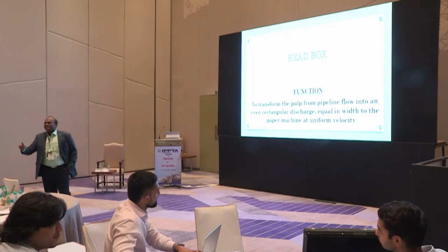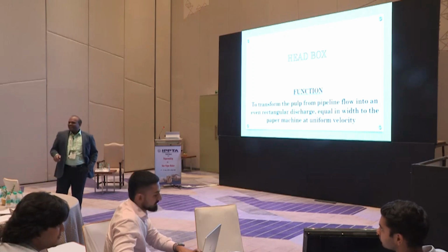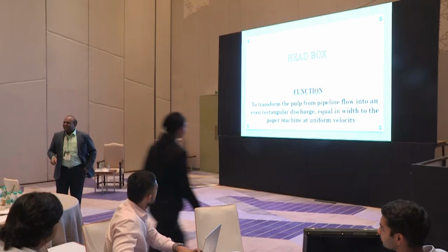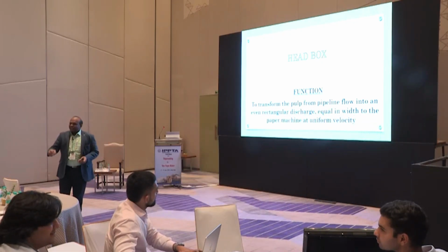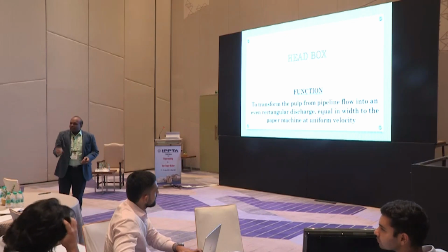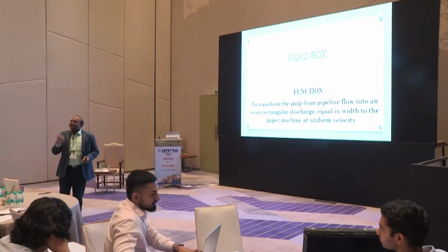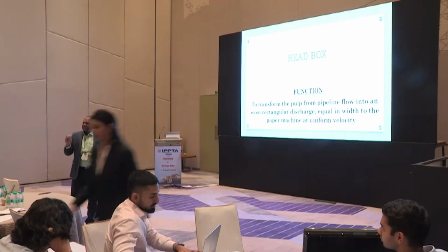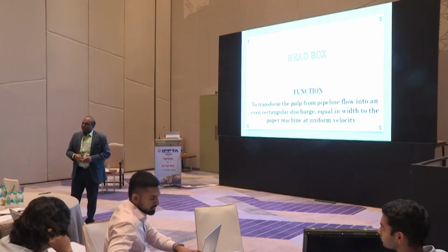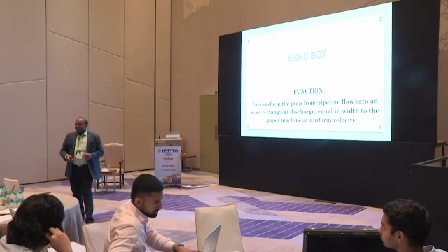It gives additional smoothness. There is a technology derived from washing clothes. It has been copied from washing clothes. The ironing man used to spray water to make the fabric much smoother. Similarly, before calendering, we can use water showers or steam showers. It's not a water shower, it's a slight steam shower technology that is available, so that we can increase the paper smoothness before calendering.